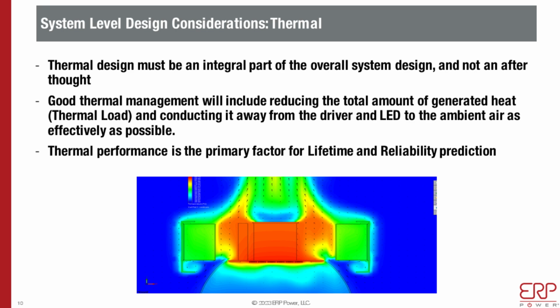So on thermal, obviously you don't want to do what I've seen over and over, where the thermal design becomes an afterthought. It has to be thought of right from the get-go. Actually, to me, thermal design is the primary factor that determines everything else: your lumen output, efficiency, cost, and a whole bunch of other things. So you have to think about it right from the get-go and make it part of your design.